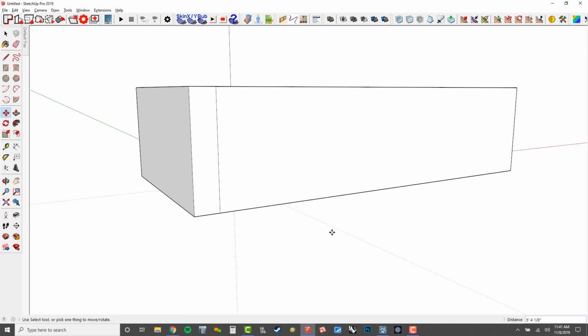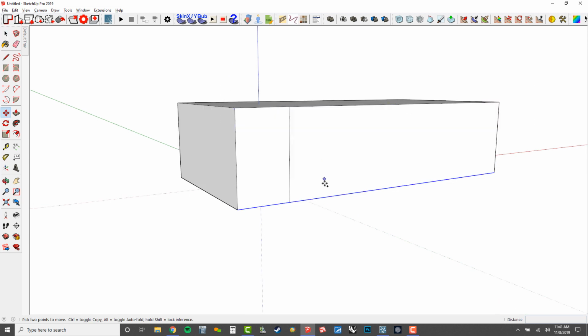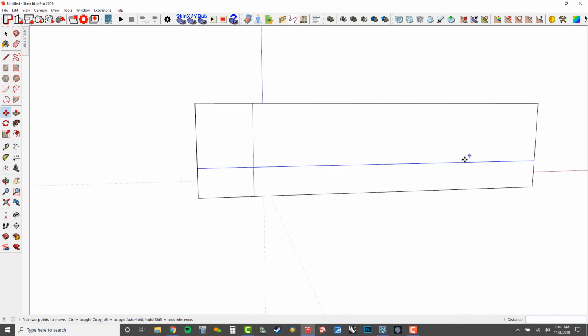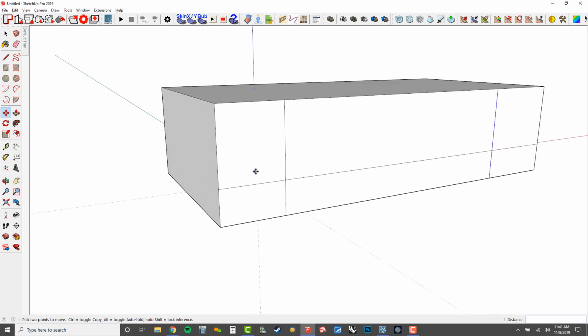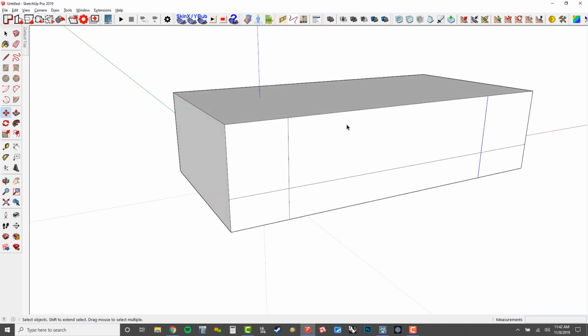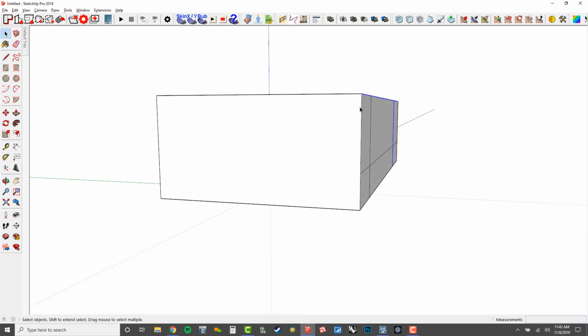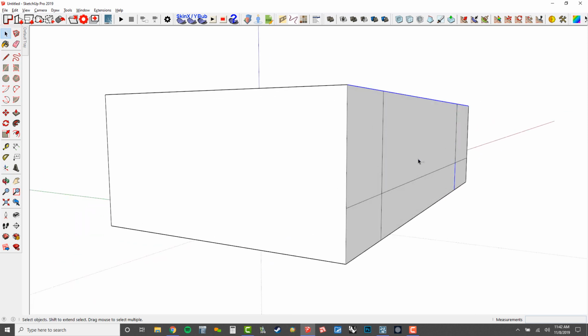All right, so then I'm just going to start kind of pushing and pulling this thing around. I'm going to copy this over here by, say, 15 feet. We're going to make a copy of our bottom edge, take that, move it up by, say, 8 feet. And then I'll take this edge over here. This is kind of how I work. I just do some construction geometry. I'll say like 20 feet. And let's see. Then the whole roof line, I'm going to bring that down and pull it out. I'm going to make this roughly a 3 foot drop here. So let's say 3 feet.